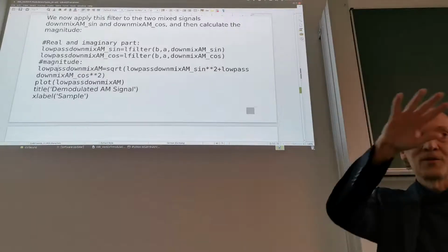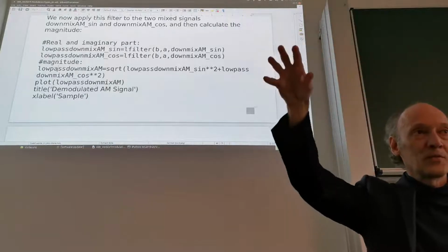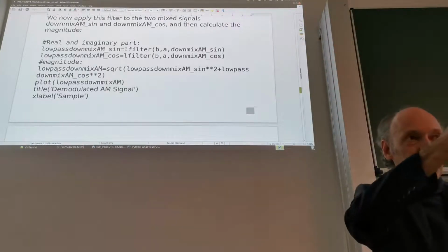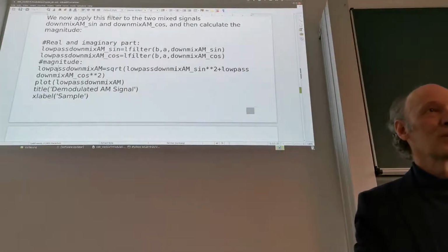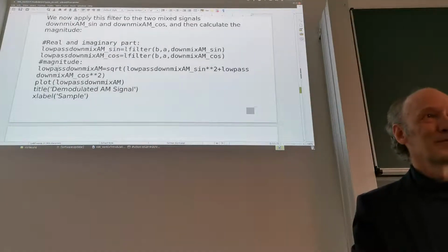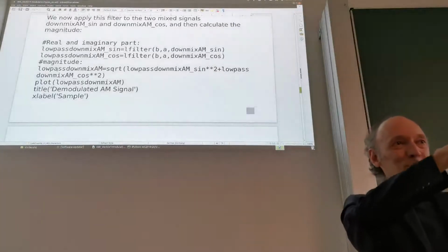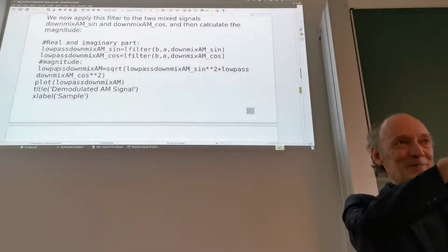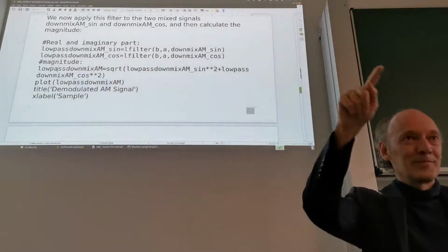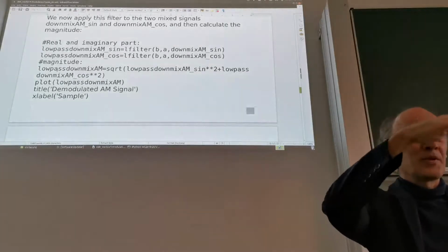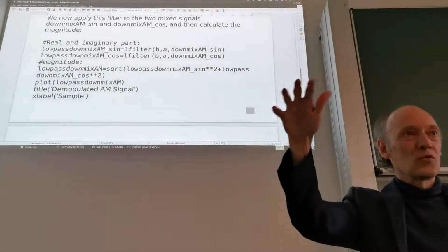Remember, this part had our sine wave, the slow sine wave, and below it, it had this dense carrier wave. So after low-pass filtering, what will we get? We're going to receive the original signal that we've transmitted. Basically we clean up the blue color below the line. All we will be left with is this smoothed envelope, and we will get 1 plus 0.5 times the tone.